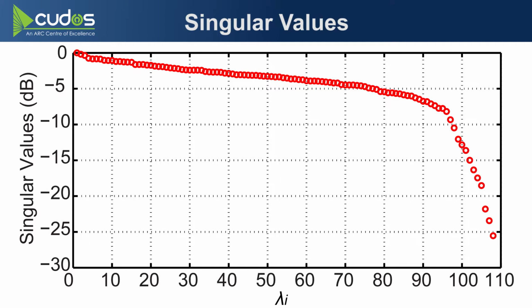Now I believe this mode-dependent loss, with the exception of those higher order modes, is more a measurement of the quality of my mode multiplexer, demultiplexer, than the fiber itself. Those lower and middle order modes should be heavily bound. Shouldn't be much loss. In particular, when you're measuring this matrix, you have to make sure that you get the phase values of the modes spot on, or you'll start to accumulate MDL. That's usually the trickier thing.